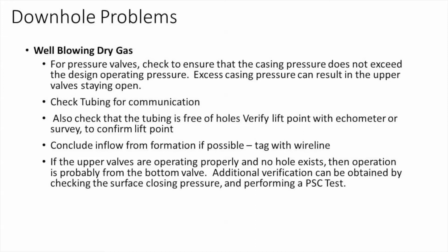We're injecting gas into the well, we're getting the gas back, but we're not producing any fluids with it. Typically that's associated with a hole in the tubing, a hung gas lift valve, a leaking point within the system that's allowing gas into the tubing above our column of fluid. So checking for holes in the tubing, checking for plugs in the tubing are the biggest way when you identify a problem by circulating injection gas.